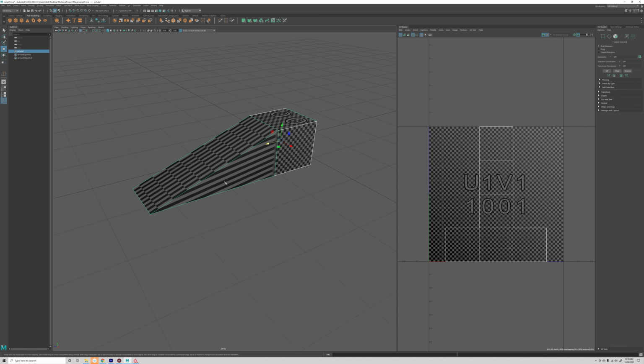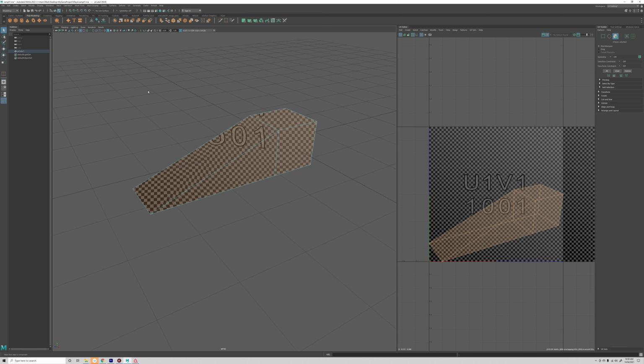So my favorite workflow for unwrapping, which I find very simple and streamlined, is essentially a three-step process. We always want to start by projecting. So UV, and I'm going camera based. So that projects new UVs onto our model with no seams. You can see how this is a 3D object and this is a 2D object, how they relate.